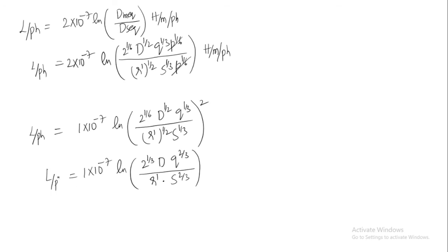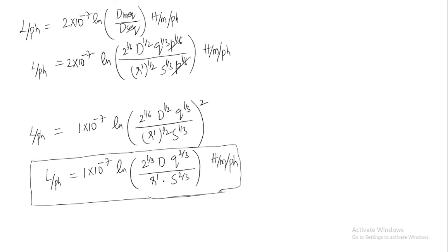It is the inductance per phase of an unsymmetrical double circuit line arranged in a vertical fashion, with the vertical distance as d, and the smallest diagonal distance is q and the largest diagonal distance is s, with the radius as r. So now what is r dash here? R dash is nothing but r dash is equal to 0.7788 times r.